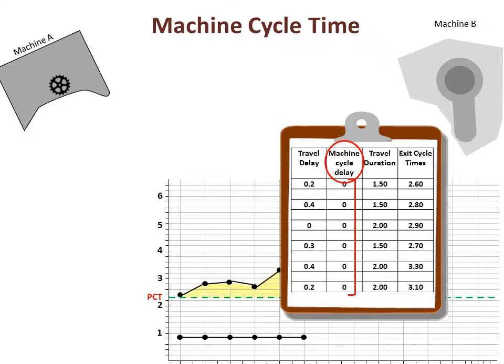We weren't surprised that our machine cycle times were consistently the same each cycle. Generally, you only see differences in pure machine cycle times when there is a significant difference in the material or amount of stock to be machined. Worn-out machinery can also cause issues with machine cycle times.